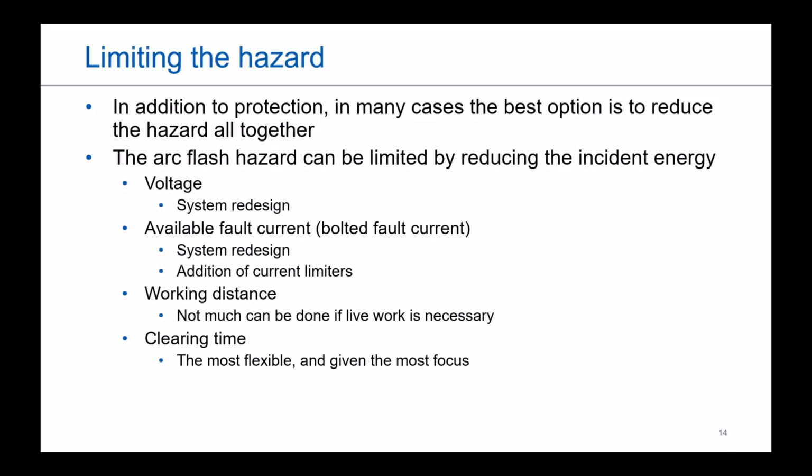You look at working distance. Again, if you're having to do live work, there's not much you can do there. You have to be in front of the gear. You're only going to be able to do that from a certain distance, and you're probably going to be within the restricted boundary. Again, not much you can do there. So really what that leaves us with is clearing time. That's what is the most flexible, and that's what gives us the ability to work around what the available levels are, because we can modify what that clearing time is. And as technology continues to evolve, I imagine the ability for equipment to respond is just going to improve further, and we'll see even better capabilities than what we see today.